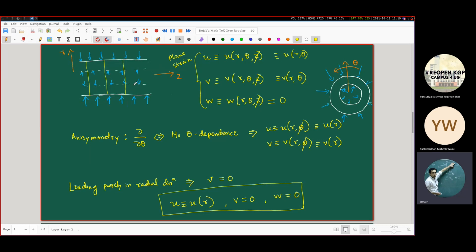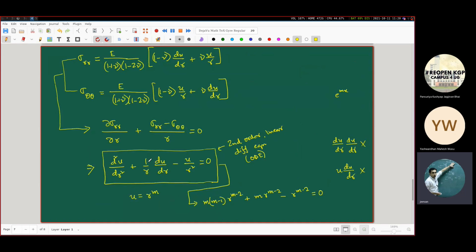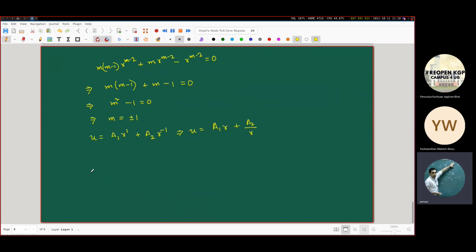If you think about it, the situation is like this. The actual loading conditions are in the form of the pressure. That pressure is basically like a sigma RR, a stress in the radial direction. So at the outer radius, you have some value for the sigma RR, and at the inner radius, you have another value for the sigma RR. And perhaps it is all right to provide our boundary conditions in those terms, and you will see that it is actually enough.